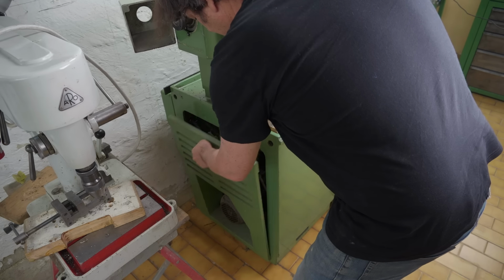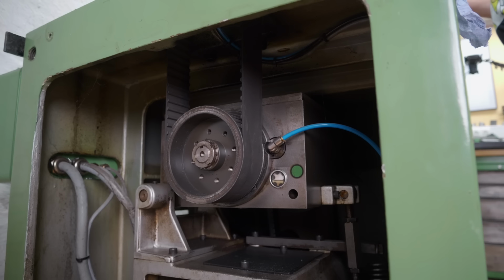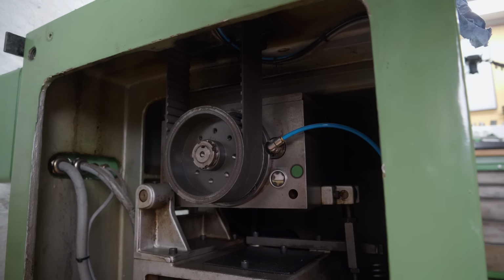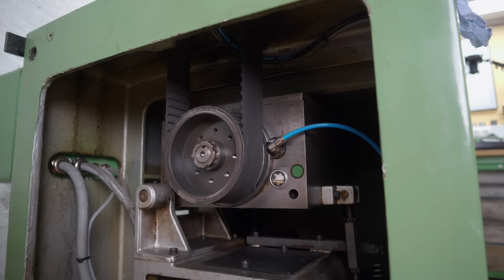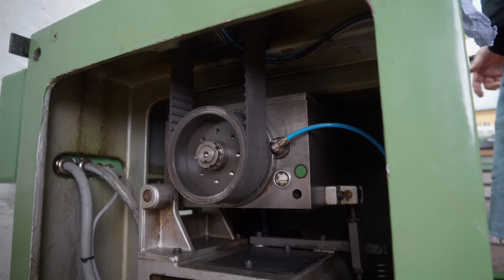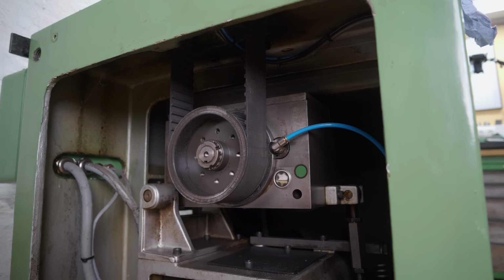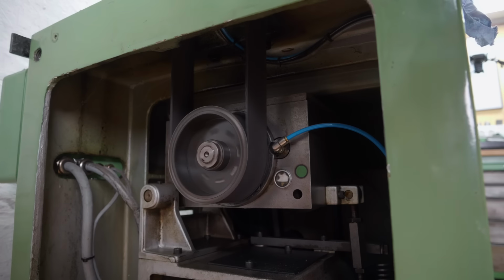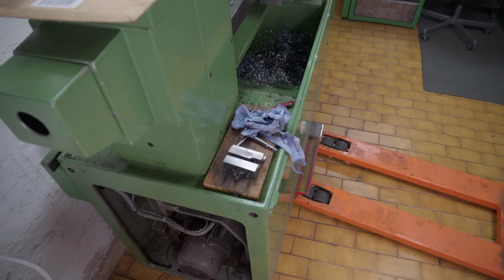Alright, let's take a look at the belt. Okay, motor's running and nothing's coming out. That's not good. Have no drive coming out through the drive system. That looked kind of wobbly. Now I need to look around the back at that CVT, don't I?